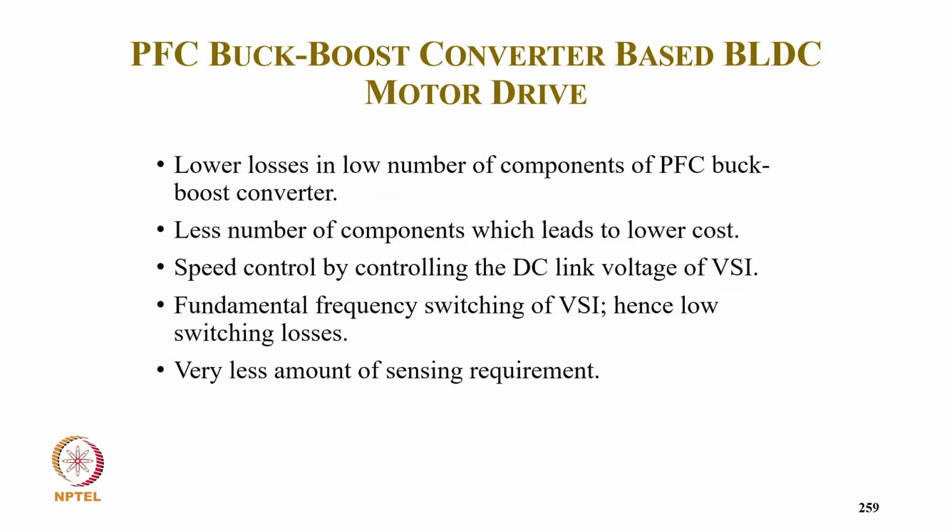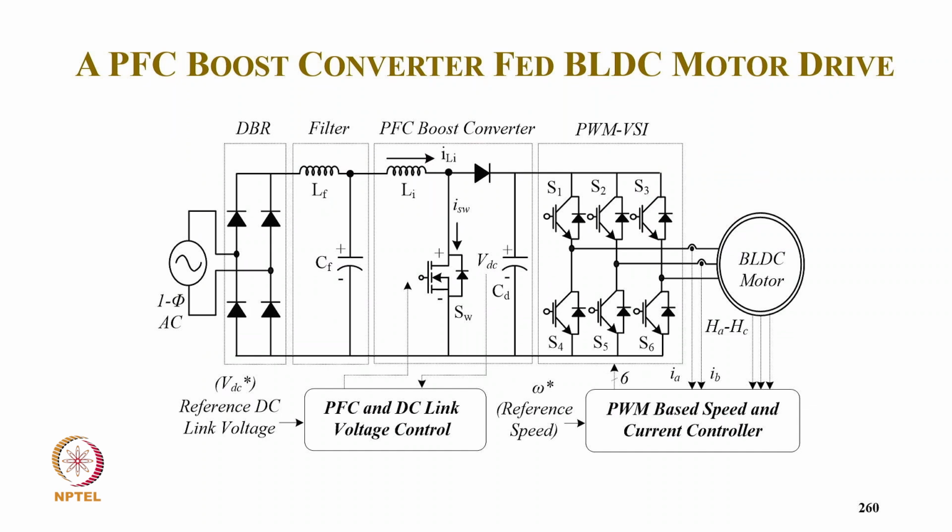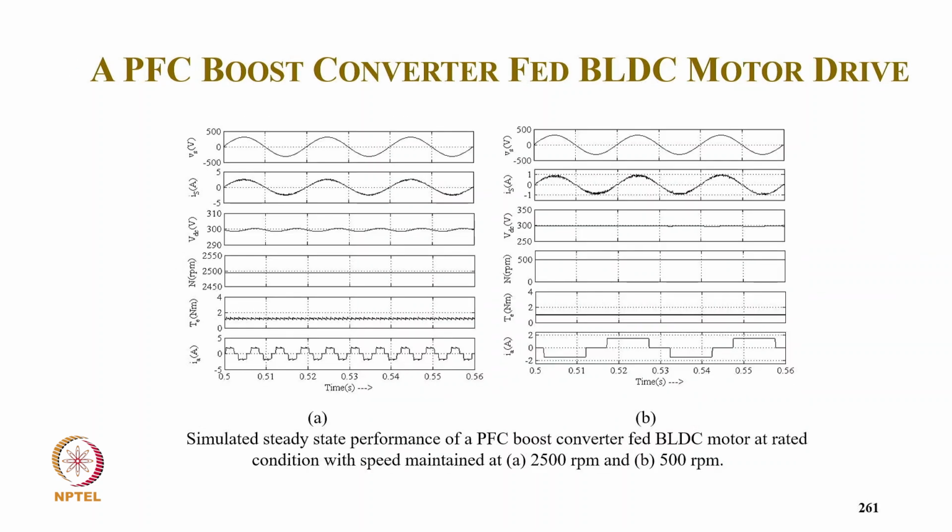So what PFC buck boost converter based BLDC motor type, it lowers the losses, the low number of components in PFC buck boost converter, less number of components which leads to lower cost, and speed control by controlling the DC link voltage of voltage source inverter, and have a fundamental frequency switching of VSI, hence low switching losses and very less amount of sensing requirement. And this is typically your PFC boost converter after diode rectifier, and then we have a PFC boost converter followed by your PWM controller, and this is typically the waveform of PFC boost converter.